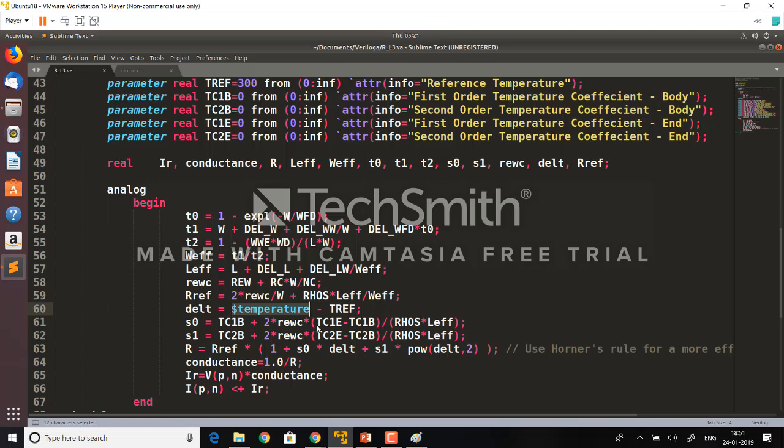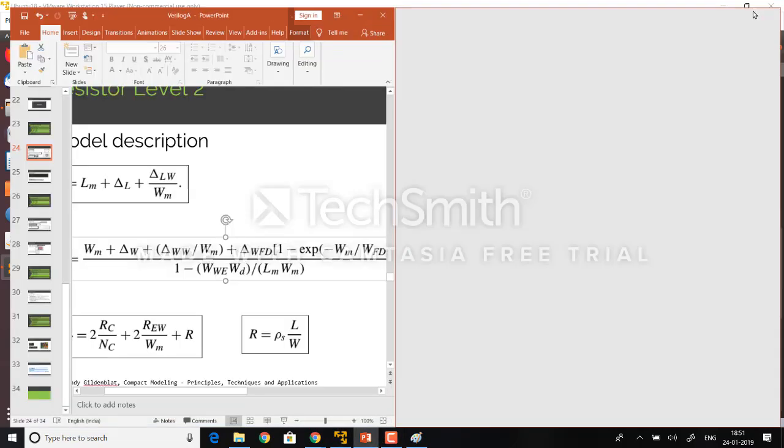Again, not parameters. Whatever you mention in a DC statement in Spice comes down into this variable there. It's a standard variable, you can't change it. Whenever you want to know what temperature is being sent from Spice, this is what you use. $temperature. Okay. Okay, for this one, let's move to the next model I have.